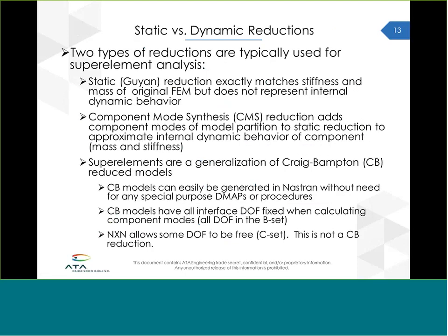Dynamic reductions, I've kind of referred to these terms earlier. The two type reductions, one of them is static. You'll see static and Boolean, those are really the same thing. When you make a static reduction, it is exact in terms of the mass and stiffness. So you lose nothing, there's no loss of accuracy between your boundary points. But because, as the name implies, it's static, it does not attempt to represent the internal dynamic behavior.